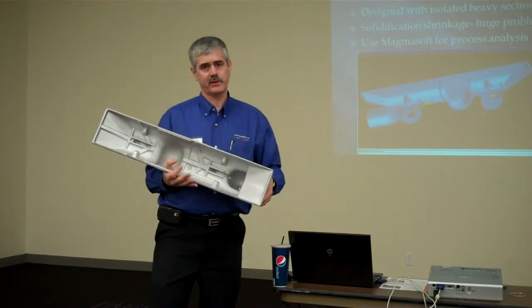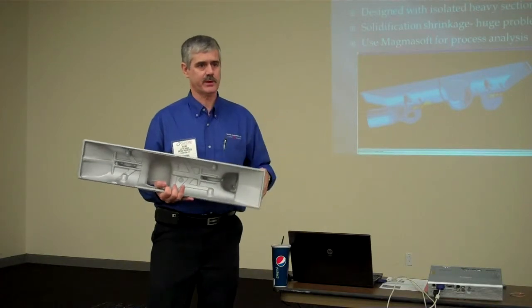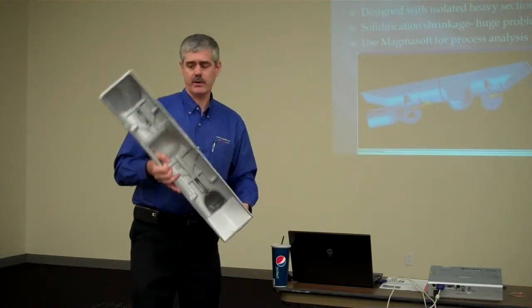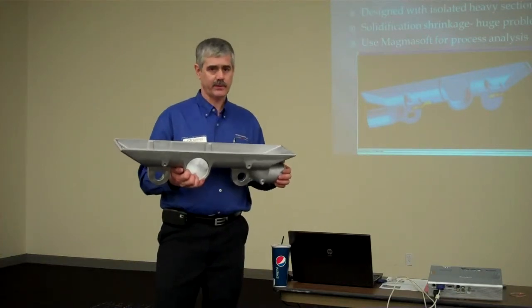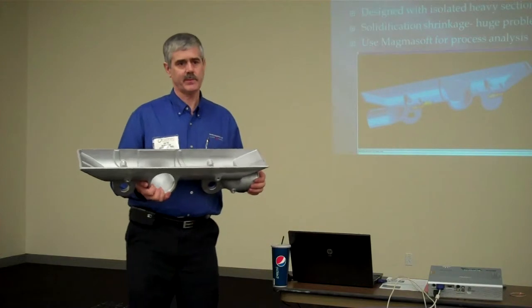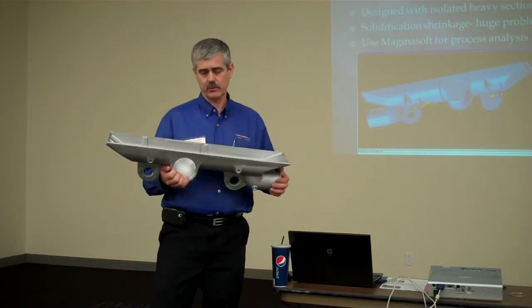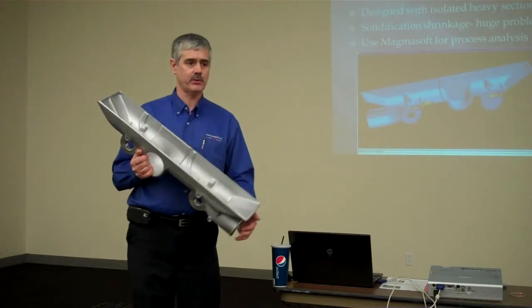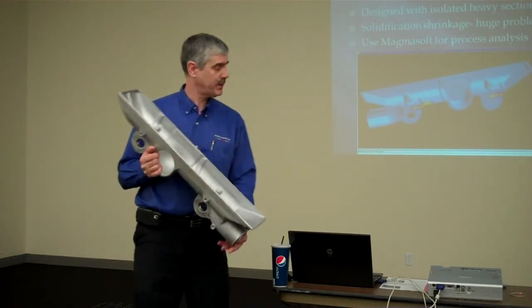And solidification modeling is a computer analysis to see whether you can make a good part before you cut a mold and start sort of learning by trial and error. It allows us to really identify, will the casting process we're planning make a good part? And it can avoid some expensive mistakes. It can shorten your effective lead time by getting you so close to making a good part the first day, you don't have to plan for pulling the mold, making a gating change, cooling change, and running a second time.